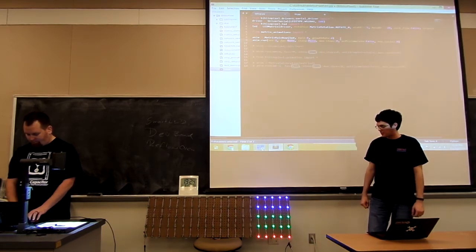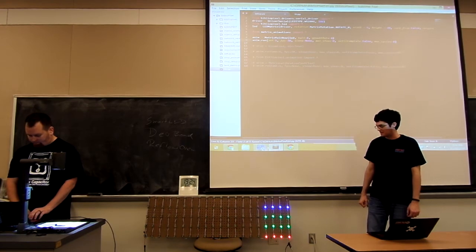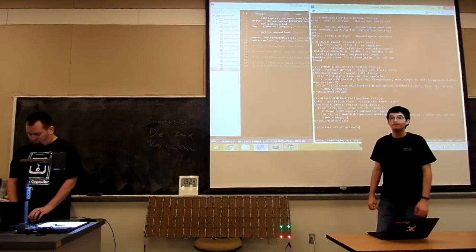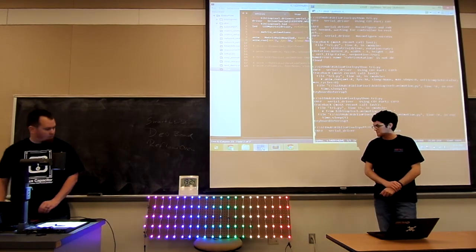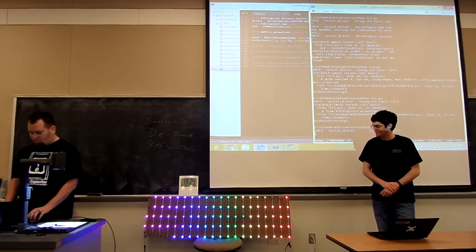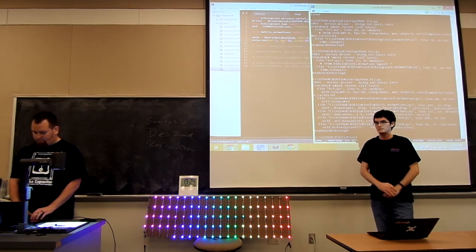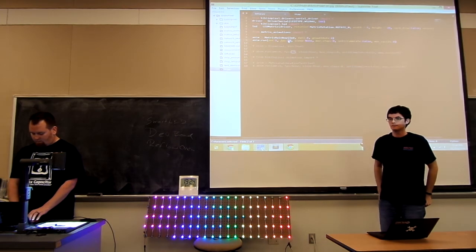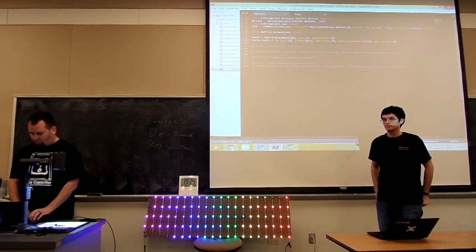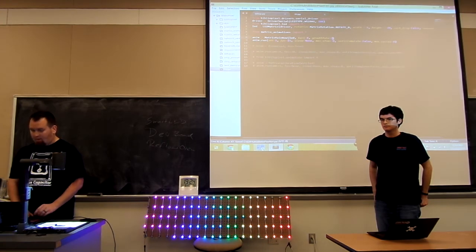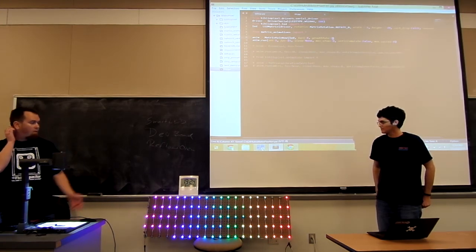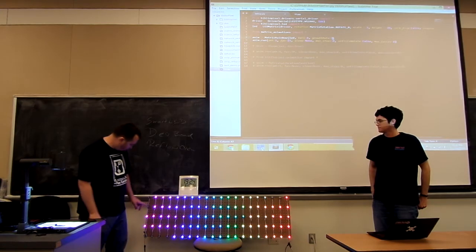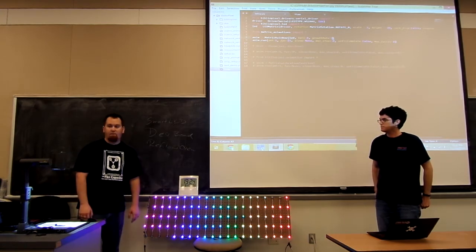So just a quick word on powering the LEDs. Can I ask a question about the shifting before you go to power? That's awesome, but how does it say light? I mean, you say you shift it in, but as that data shifts down the register, it seems like each one would light, because you have blank ones there in the chain. Well, because what it's doing is, for this one, this blank right now, it sent it 0, 0, 0.